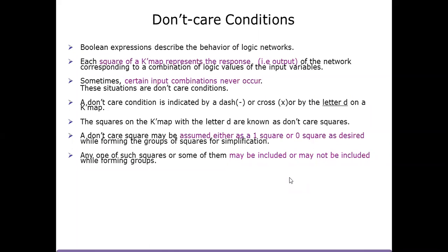Sometimes it can contain input combinations that never occur, because these logic circuits are not virtual things. They are real physical devices. However, it would not work for some input combinations. Those input combinations are called don't care conditions.